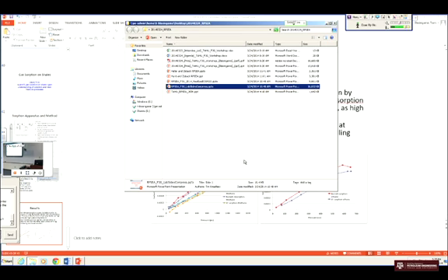We never figured out how to get what you want, which is fracture dimensions. What we really figured out we could use it for is to figure out when the frac was open and closed. So we tried to use this to corroborate closure picks from mini frac data. Because when the frac was open, you got a certain type of reflection, positive or negative, I can't remember. And when the frac was closed, you got a reverse polarity of that. So that was pretty easy, but the different dimensions were never anything that we figured out.